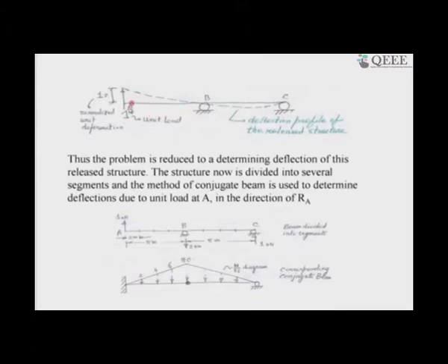So, if it is restrained here from upward movement and restrained here from upward movement, in both places, then as this goes up, to have the geometric compatibility of the beam, it will take a curved shape like this.